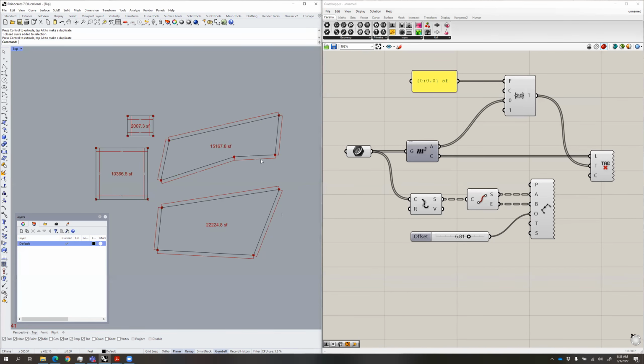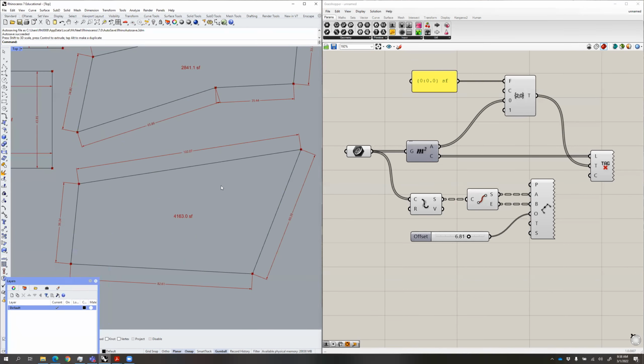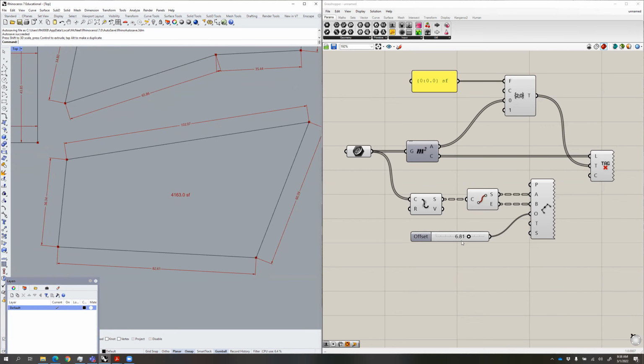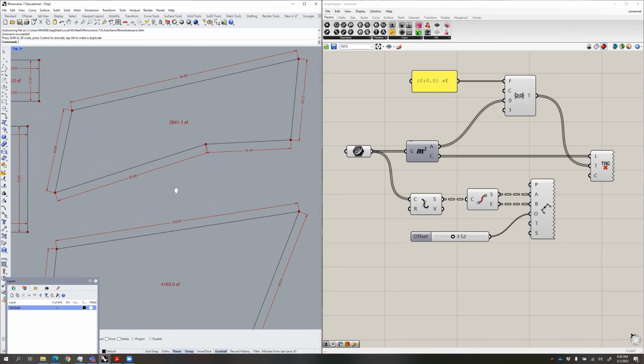If I zoom into that, let me do this actually. Let me take these. These are kind of huge. Let me take them and I'll just scale them down a little bit, like so. Okay, let me zoom into that. If I zoom into this now, you see what happened is now we've added a little dimension line around each of these lines here. So this is the foundation of layout plans, right? If any of you ever work at a firm in the future, you're going to create a lot of these layout plans. You just need to take geometry and you need to tell the contractor how big is it, how long is it on one side, how long is it on the other side, and then obviously you need to tell them what's the angle between each of these lines too.